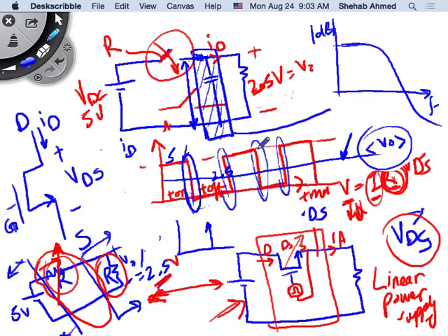So if I'm able to design a low-pass filter with good gain for the average value at low frequencies, it passes the average value through, so my DC signal will go through nicely. What happens to my higher frequency components? They are attenuated. Do they suddenly disappear?